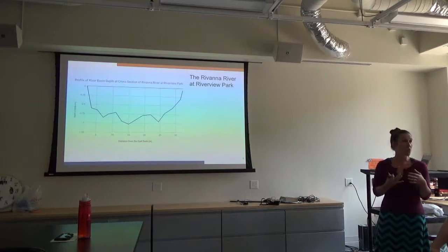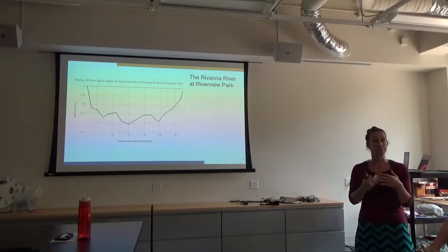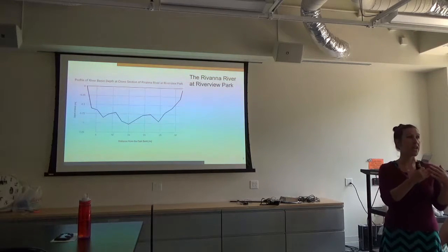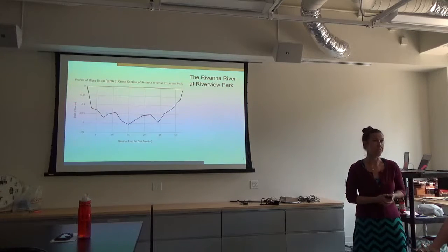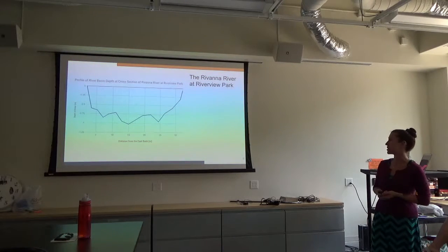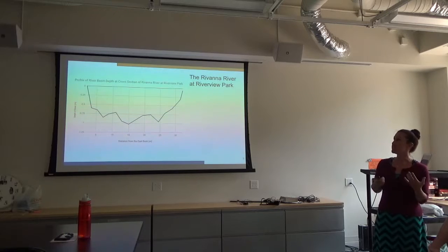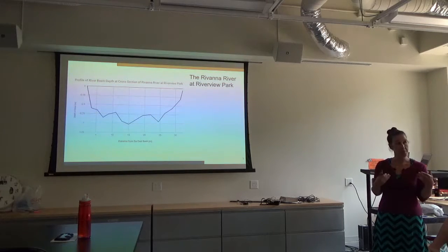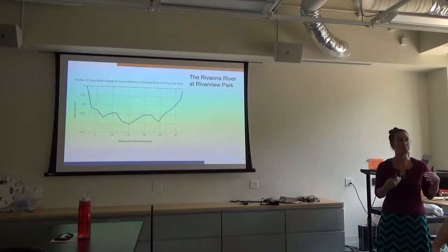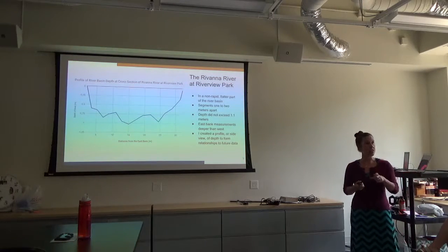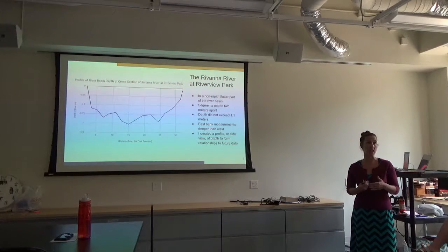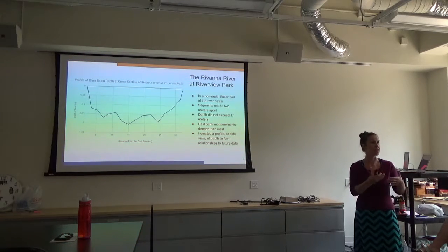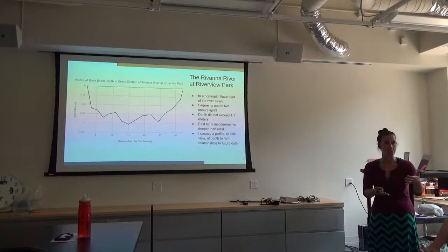So I'm going to start with the data and what I received from this. I started off with creating a cross-section, or a profile, of the depth values that I collected at this particular region. I strung tape across the width and measured at segments of 1 to 2 meters across each area's depth, and what I found is that the east bank of the riverside had the pool, or in this case, the deeper value for the depth.